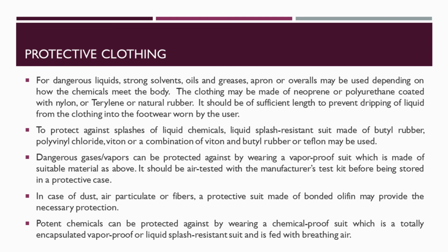If the chemicals or chemical operation pose explosion or fire risk, the protective clothing should not be liable to increase the possibility of serious burns, such as avoiding those made of synthetic materials that may melt in a fire and thereby causing more serious burns. Protective clothing may be of the reusable or disposable type. It should be noted that the materials mentioned may deteriorate due to the aging effect.